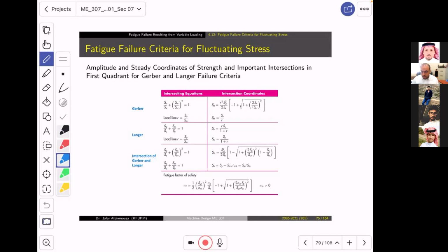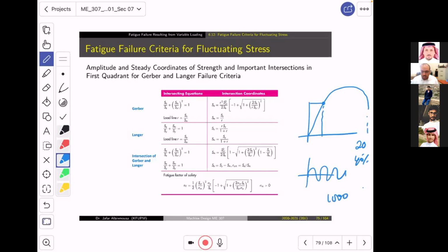Can you believe it? Guys, the stress strain curve is like this, very big. It can reach 20%, 40% strain. But what do we say? At the yield, which could be less than 1%, maybe 1% maximum of strain only, if you apply this load in a cyclic fashion, you will probably get 1,000 cycles, no more. Probably. That's a general wisdom.